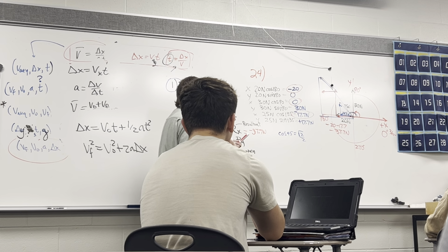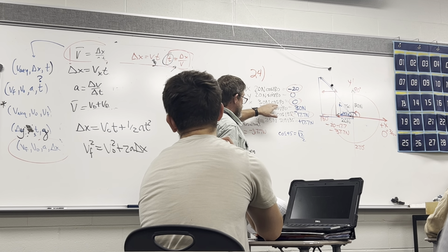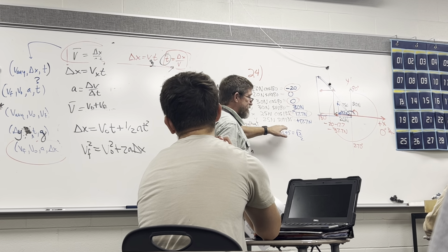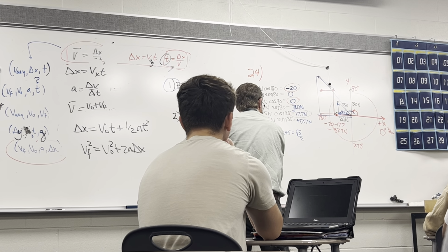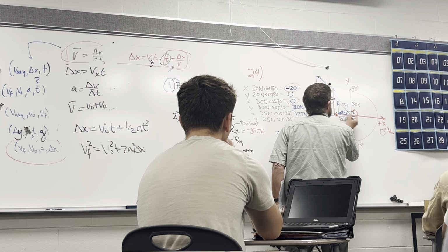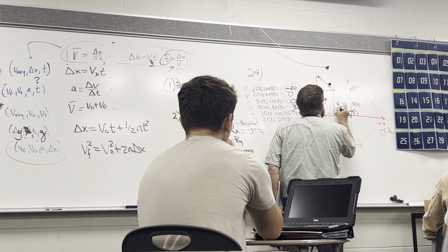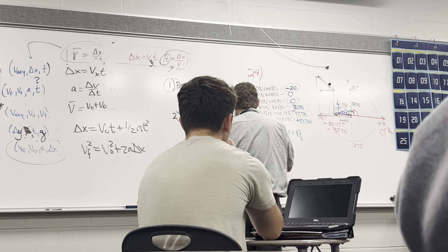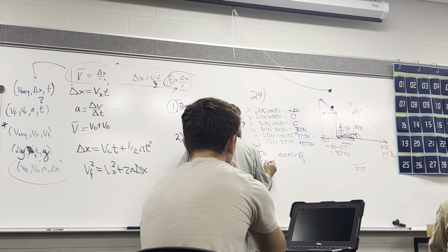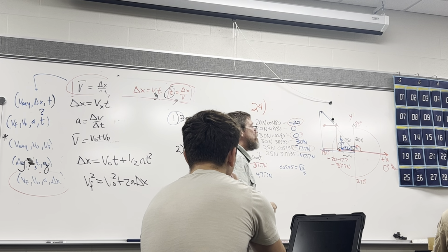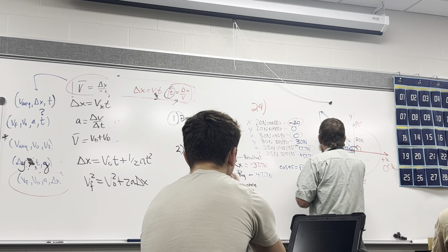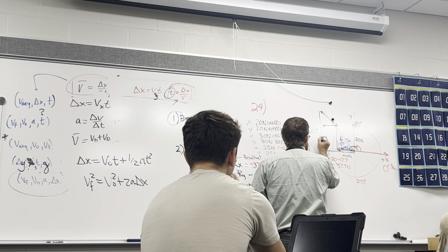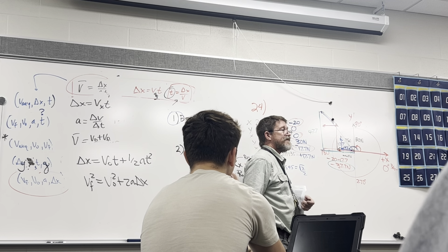And then, look at your Y's. 0 plus 30 plus 17.7. So the Y parts, I'll do this in blue, that's going to be none plus 17.7 plus an additional 30. Your Y parts end up being 47.7 newtons. Now we have a giant triangle. I need to do color because it gets crowded here. We have a giant triangle whose sides are 47.7 and 37.7.